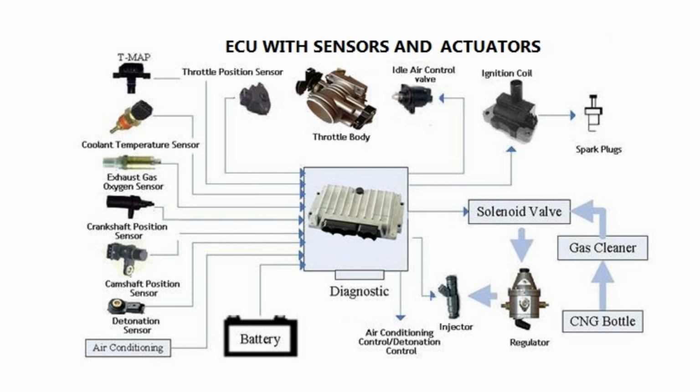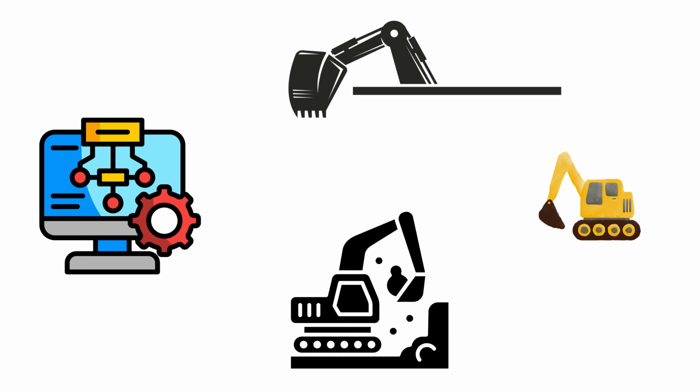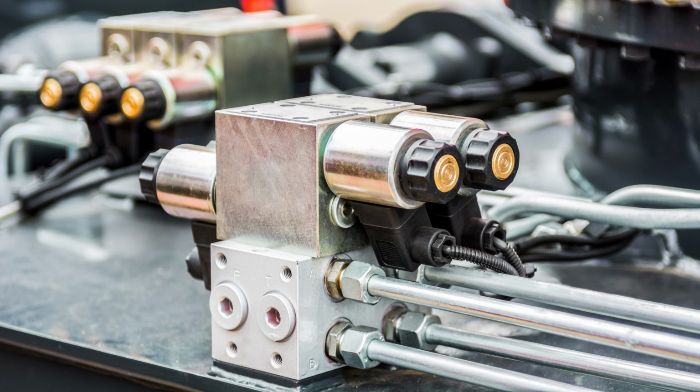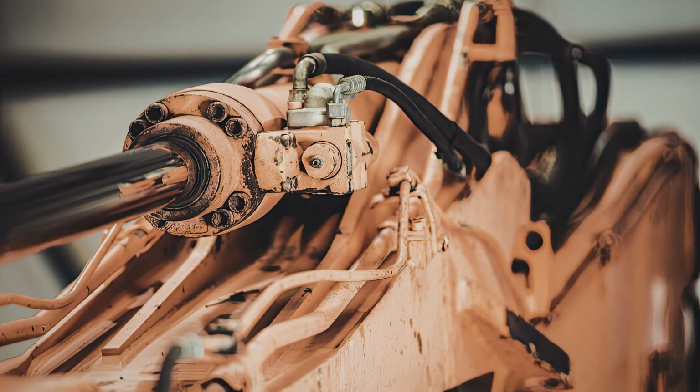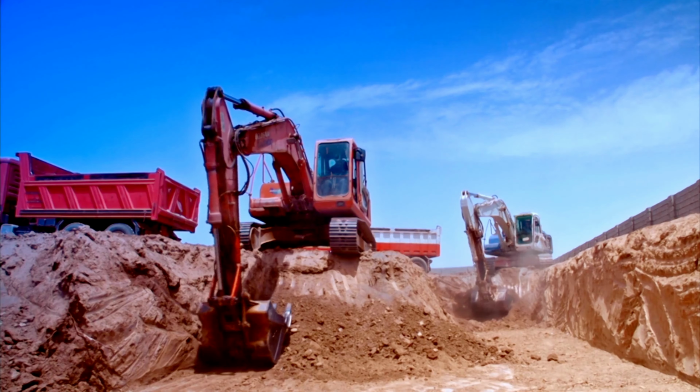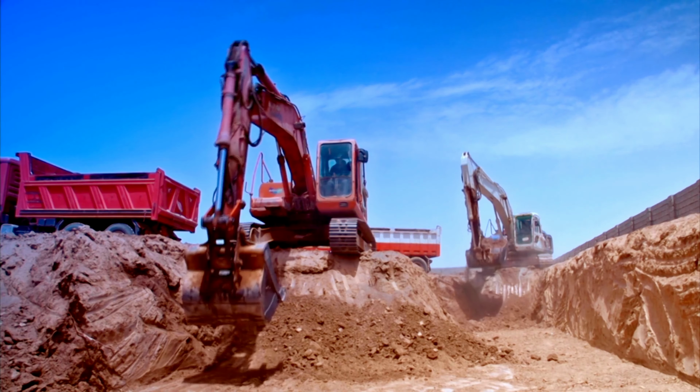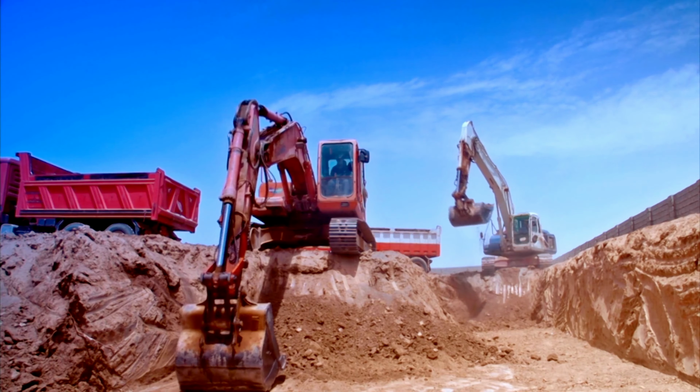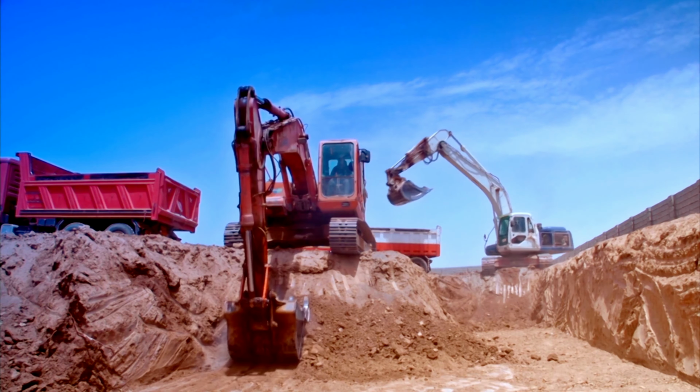linkage. All sensor signals are transmitted to one or more electronic control units, ECUs, which act as the central processing units of the machine. The ECU processes incoming data using control algorithms that determine the optimal hydraulic response for the current operating condition. Based on this analysis, the ECU regulates electro-hydraulic proportional valves which precisely control the flow and pressure of hydraulic oil delivered to cylinders and motors. By adjusting these parameters dynamically, the system ensures smooth motion, efficient energy usage, and improved controllability of the machine.